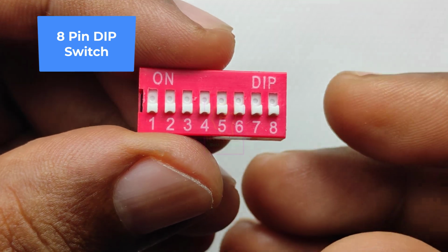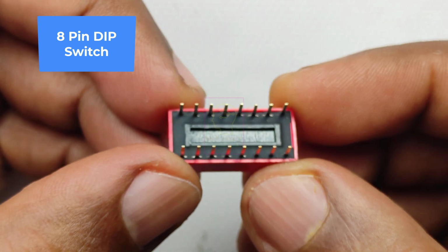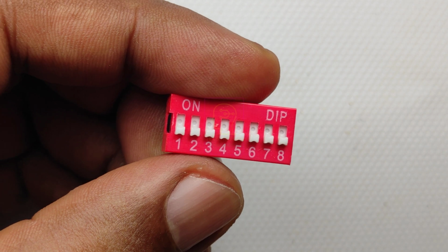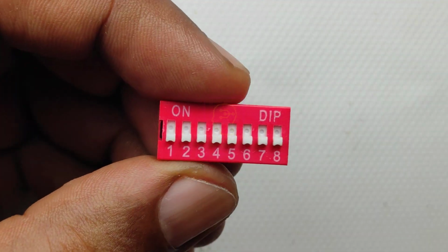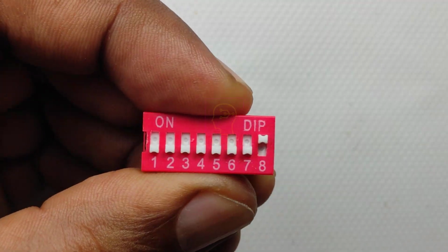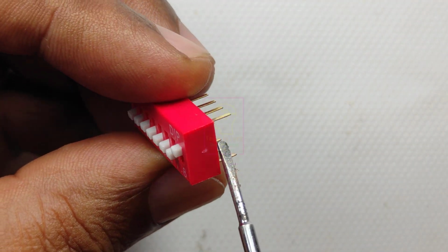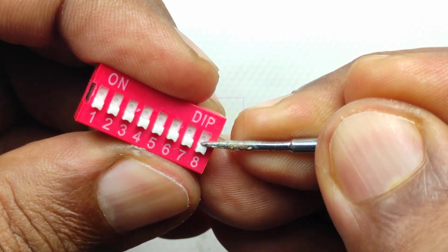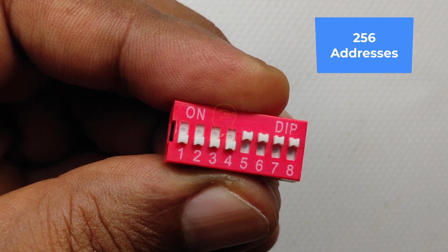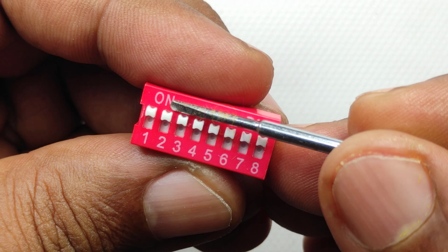This is an 8-pin DIP switch which is used for fixing the address of the HT12E encoder and HT12D decoder. In my earlier RF videos, we used fixed address for HT12E encoder and HT12D decoder. But here we can fix any number as address. By sliding each switch, we can change the address of encoder and decoder. Since it has 8 switches, we can create 2 raised to 8, which is 256 valid addresses for decoder and encoder. Please watch the video completely because I will be explaining a lot of things while assembling.